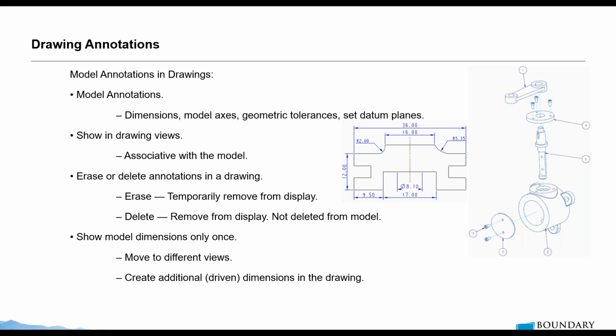Everything is concentric. Okay. If you add dimensions, if it's a driven dimension, then it's not linked to the model. Then it's linked to the entities in the drawing. Okay. So you can create additional dimensions in your drawing. You don't have to pull everything from the part.